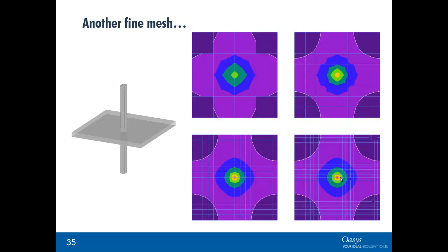The thing to remember is this is an area where FE diverges from reality. Reality is columns have dimensions, slabs have a thickness, and the moment will be occurring not over a mathematical point, but over the interface between the column and the slab.